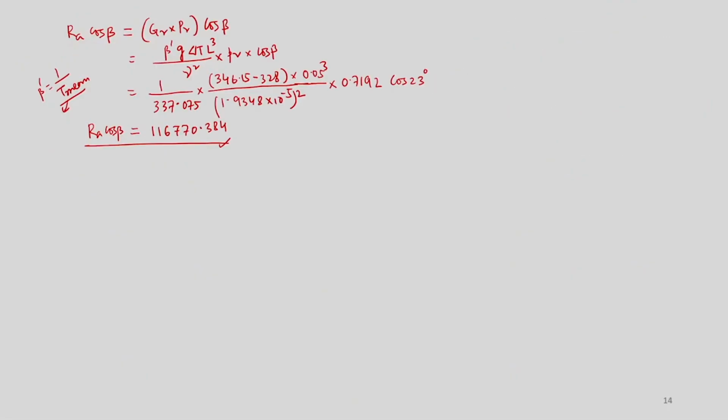So, this correlation, Nusselt number is equal to 0.157 times Ra cos of beta to the power of 0.285. Okay. Since you have already understood what is Nusselt number and other parameters, then straight away you can calculate what is the heat transfer coefficient. So, this is nothing but h_PC1 multiplied by characteristic length L, divided by K, where K is the conductivity.